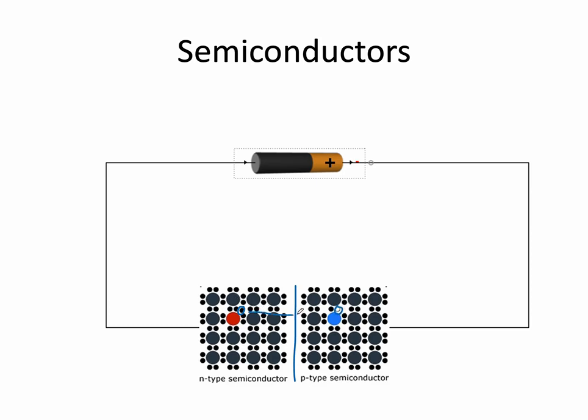Electrons are naturally going to flow across this way to replace or fill up all the holes. And if you just left these 2 pieces of silicon in contact with each other, yep, the extra electrons here would fill in all the holes they could over here, and then the whole process would stop. But here's where it gets exciting. If you connect this to a battery on both sides, the battery here, this is the negative end of the battery. Electrons are going to be flowing off of this around the circuit this way. And guess what? As it loses electrons here, new electrons will flow in. And you might say, well, wait, why do electrons want to flow in here?